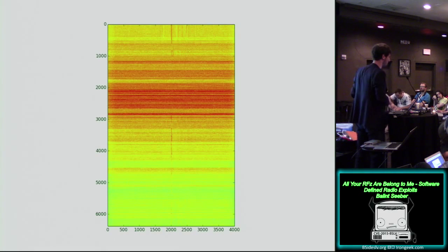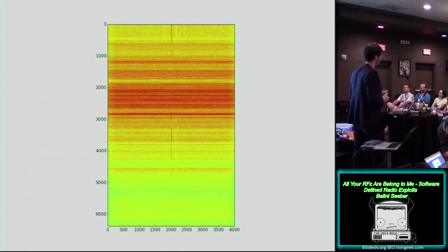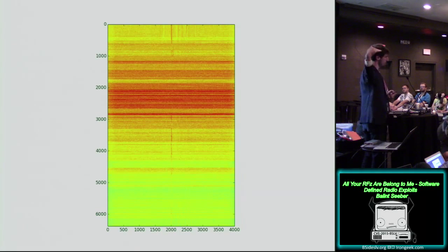I did another experiment where I ended up driving from San Francisco down into the South Bay. And every so often I would capture a bit of the signal at that frequency. And my thinking was, well, I'm probably going to pick up the direct path from the transmitter, but there might be times where I get reflections off stuff, maybe off a hill or a big building. And as I'm traveling down the highway, the distance between my car to the building to the transmitter is going to change, right? Because now I'm moving.